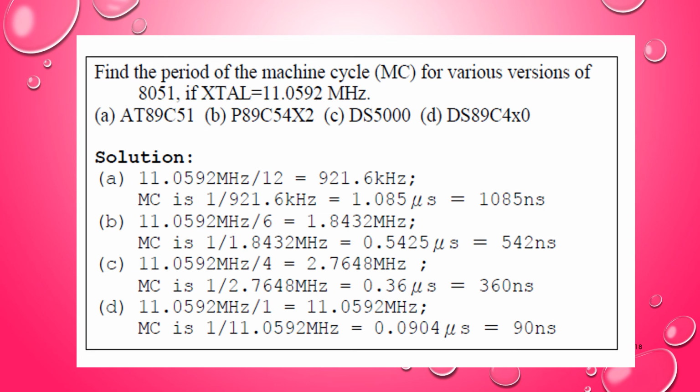After that we discussed call. There is ACALL and LCALL. So long call, long subroutine call, 3 bytes, and ACALL, absolute call, that is 2 bytes. So whenever you want to get things done faster, you can go there. We have even seen LJMP and SJMP. So long jump, again 3 bytes, the target address is relatively 16 bits, and short jump, the target address is relatively 8 bits.